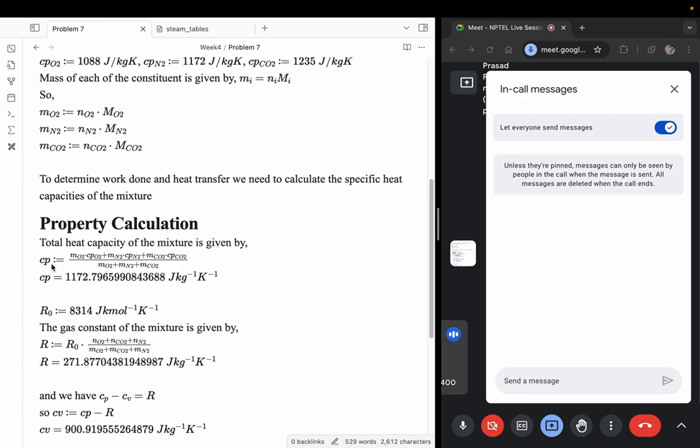So what do I mean by adiabatic mixing? It means that whenever these constituents are mixing with each other, if you consider all 3 of them to be one system, there is no heat interaction with that system across the boundary. It is as if saying there are no endothermic or exothermic chemical reactions happening when this mixing is happening, so that the total energy remains constant.